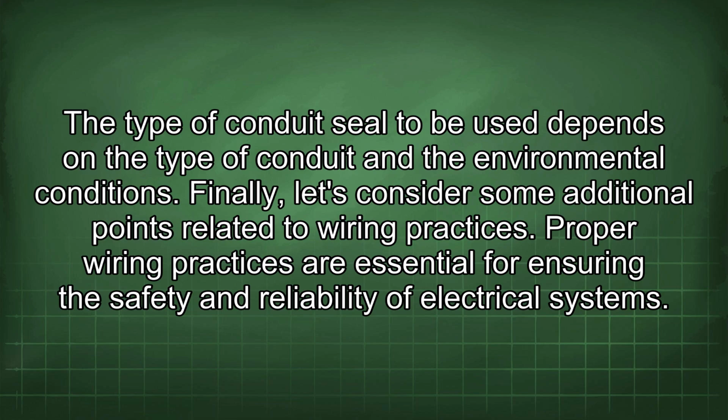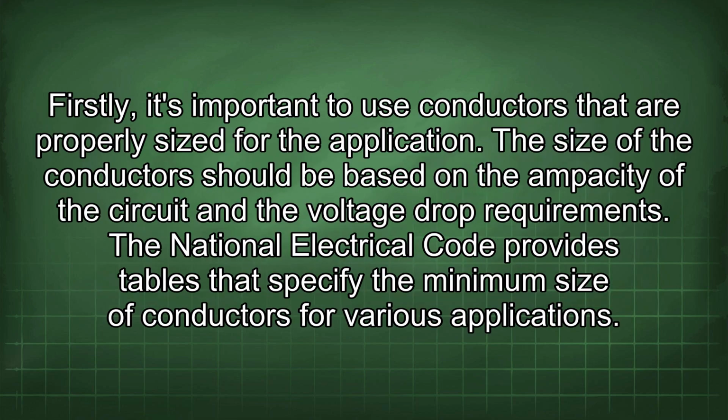Proper wiring practices are essential for ensuring the safety and reliability of electrical systems. Firstly, it's important to use conductors that are properly sized for the application. The size of the conductors should be based on the ampacity of the circuit and the voltage drop requirements. The National Electrical Code provides tables that specify the minimum size of conductors for various applications.